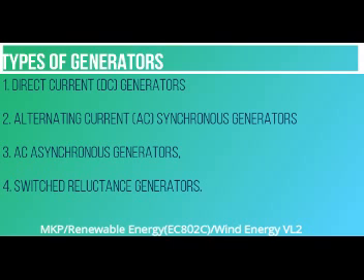Each of these generators can be run at fixed or variable speed. Due to the dynamic nature of wind power, it is ideal to operate the WTGs at variable speed. Operating a generator at variable speed reduces the physical stress on the turbine blades and drive, which improves the aerodynamic system efficiency and torque transient behaviors.